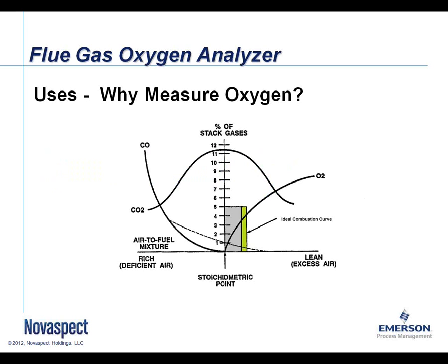So this first chart we're looking at is representative. This green portion, everything inside this box, is what we consider to be the ideal combustion zone. In your typical parallel positioning solution that Tom was pointing out, where it's all based on positions and linkages, you'll find that we tend to skew to this green area, giving away a fair amount of efficiency that's potentially available, just to keep it in a safe zone where we know there isn't going to be any issues due to changes in the air temperature or fouling or